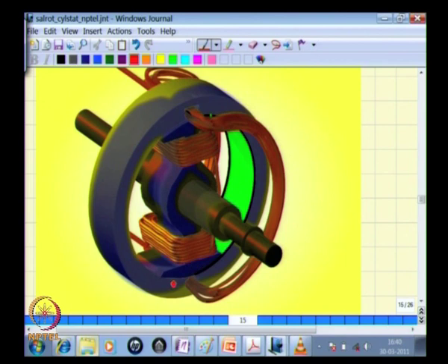So essentially what we have said is, in this region of the pole face the flux density waveform is high, and as you travel around here the flux density waveform becomes 0. Then beneath this pole face the flux density waveform acquires a negative value, and then here again it is 0, and it is this waveform that we have resolved into Fourier series, and therefore we now have a functional description of the flux density waveform as we travel around the inner circumference of the machine.